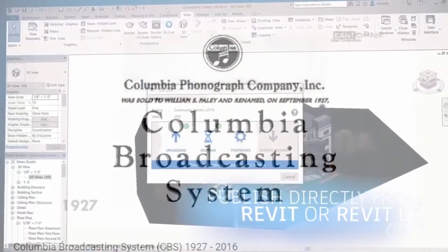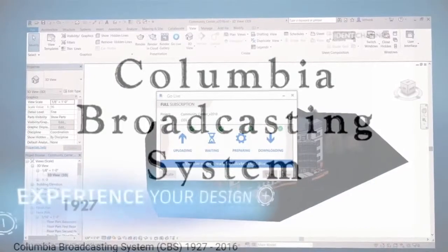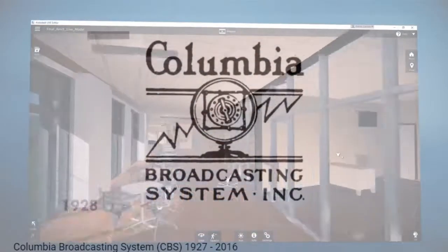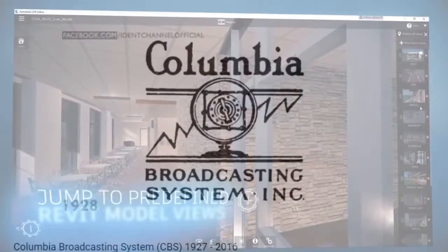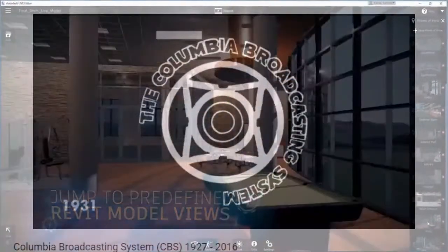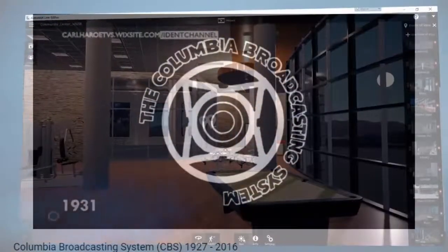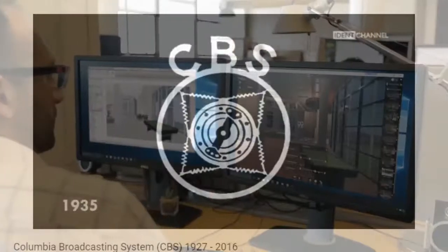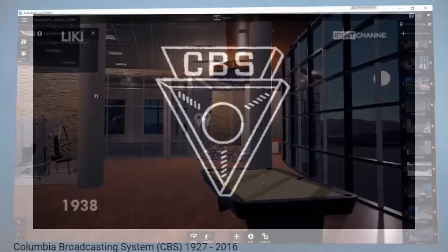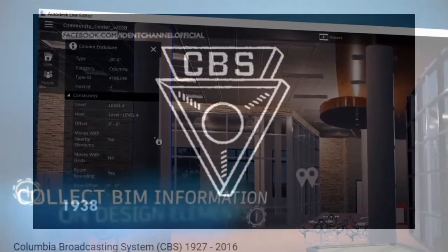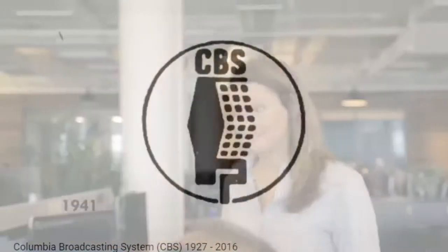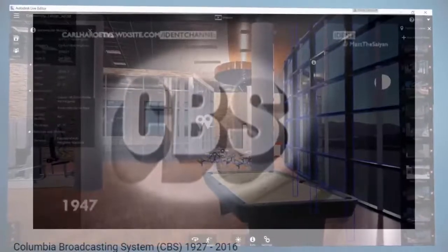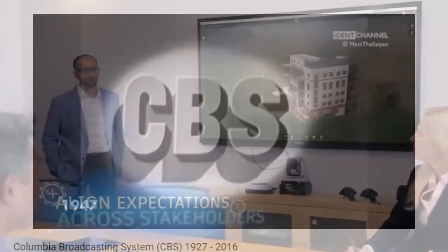If I reiterate, that's modeling in place, choosing the Floor category and creating a void extrusion where you need a slab depression. Just remember that you don't give it a negative depth; give it a level start, an offset from level, positive or negative, and then give it a depth. So if you offset it from Level +1 and gave it a depth of -6, that may work. Or if you offset it -3 from the level and then gave it a thickness of 3 in the positive direction, you'll get it cut to the underside to the flush top of slab.